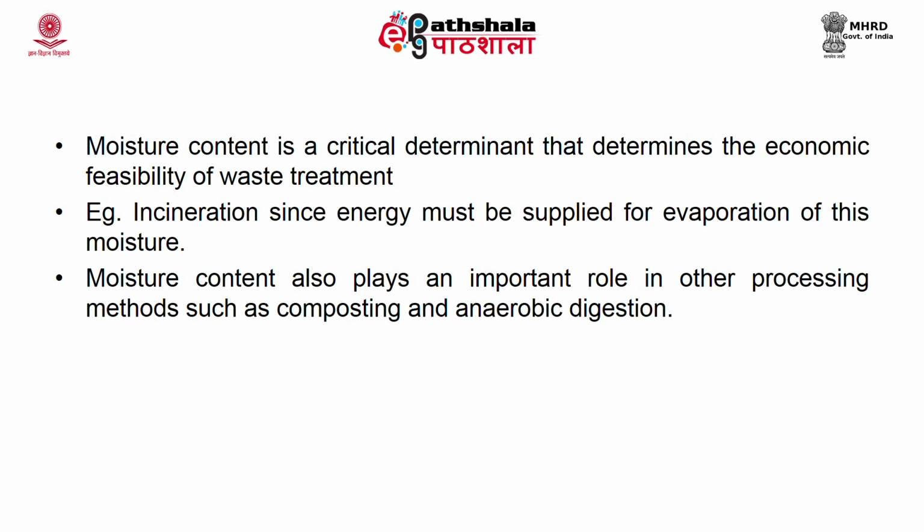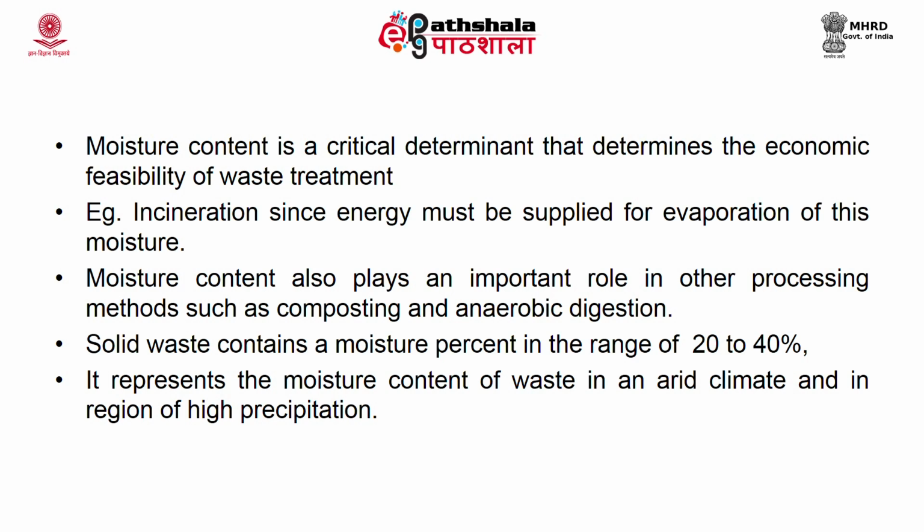The moisture content also plays an important role in waste processing methods, for example, composting and anaerobic digestion. Too much water in the waste will interfere with the composting and anaerobic digestion process. Hence, it is very essential for us to determine the moisture content before applying any treatment method. In general, the moisture content present in a particular solid waste will range between 20 to 40%.